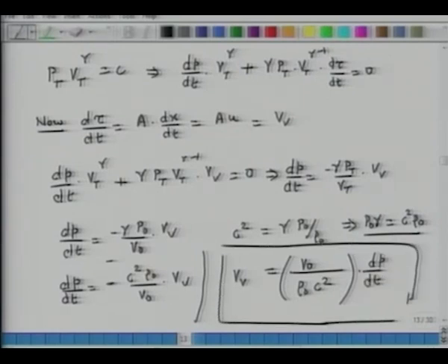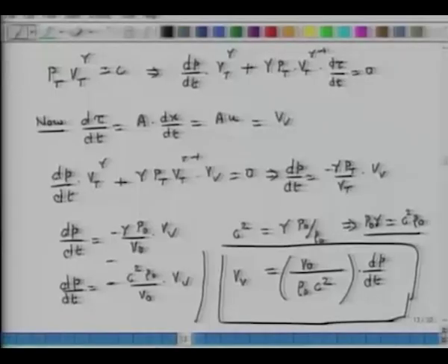What this is showing me is that a closed tube behaves like a spring, and physically it makes sense. If you have a closed volume and you put a pressure on it, it's not behaving like a mass, because mass has nowhere to go. It behaves like a spring, and we had done some earlier problems also on that. The stiffness of that is this number. This relates to this V naught over rho C square, the acoustic stiffness.